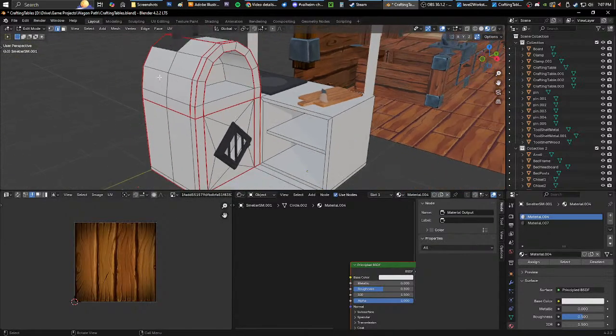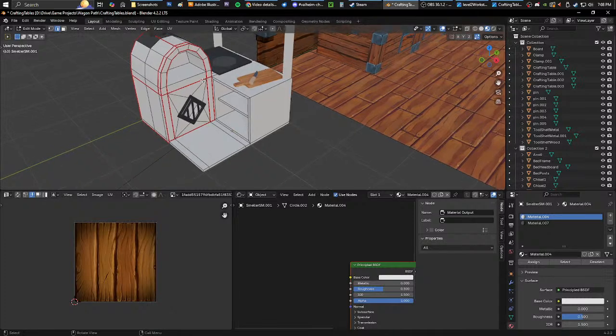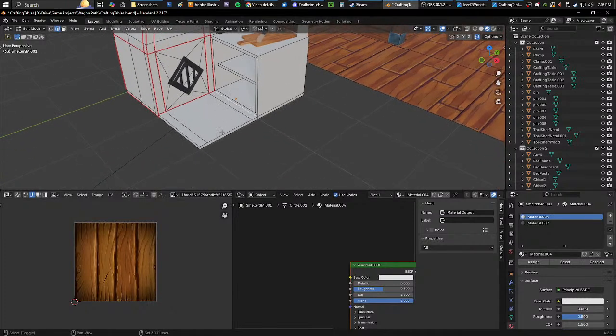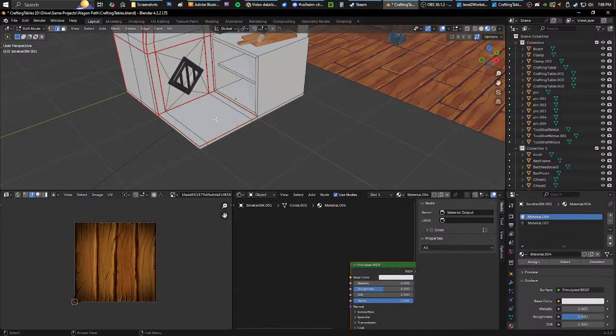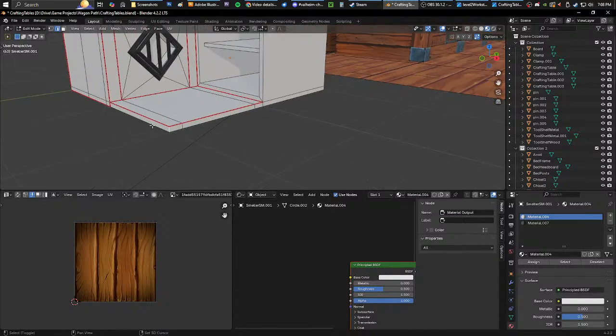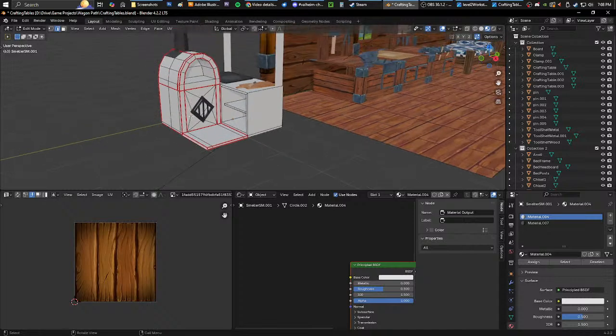So now we have, if you can kind of visualize what this will be, a smaller type of brick, whereas this will be a bigger brick, and then I can put small brick here on the texture. And then I'll do the same thing down here because this bottom piece is going to be a brick. So let me mark this seam. So now we have this square on its own, and then I'll do this one as well. So mark seam here, and then mark this one here. There. So now when I unwrap all this, these will all be their own. They'll unwrap in their own area.